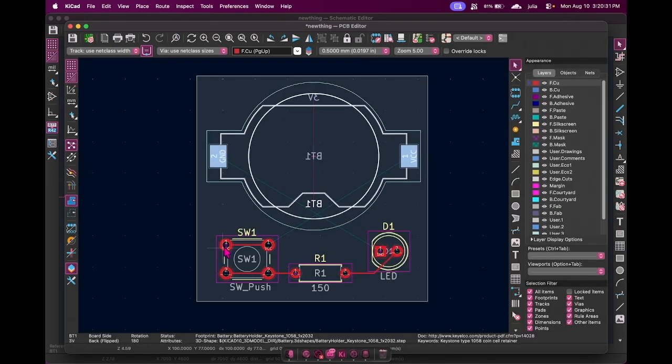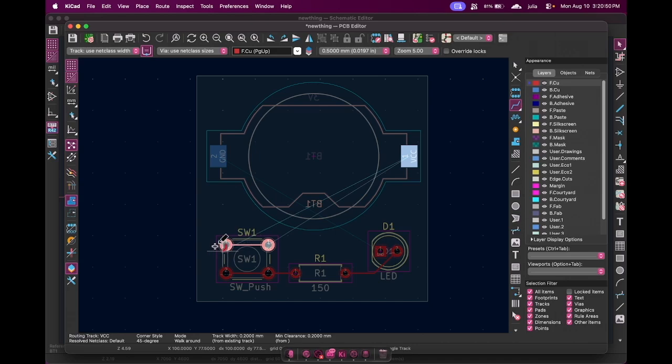But anyways, how do you wire something from the front of the board to the back? Yes, the via will let you connect it from the front to the back. So basically, how are you going to do that? You select the part that needs to be connected. It needs to be connected here, but it can't go here. Actually, it can, but it's not going to do anything, because the red is on the front and the blue is on the back. What do we do, guys?